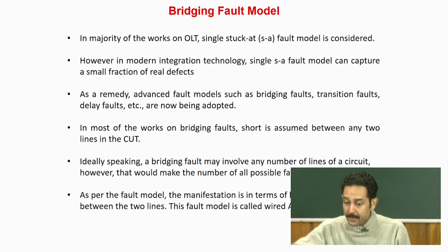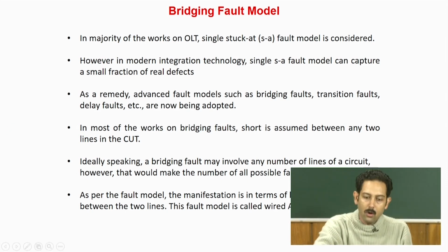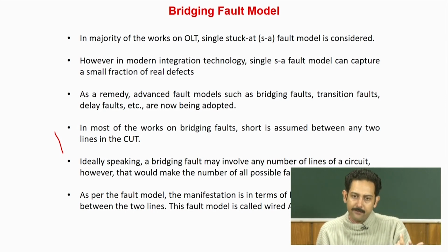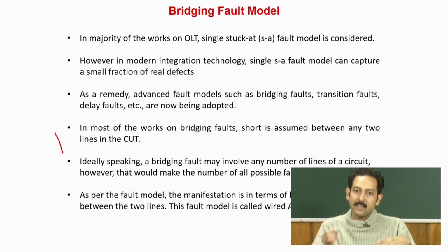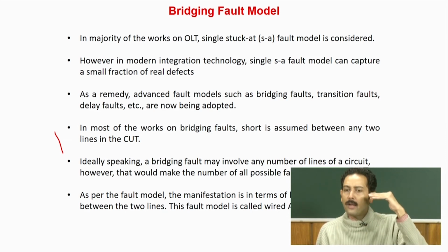The answer is no. The stuck-at fault model was a very nice and highly accurate model when it was the de facto standard and you could get very good results, when the technology was around 5 micron or more, not very deep submicron.